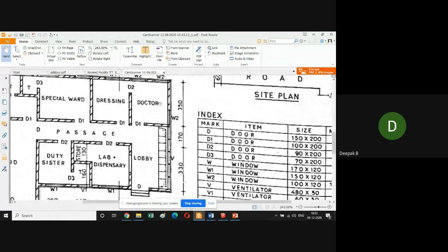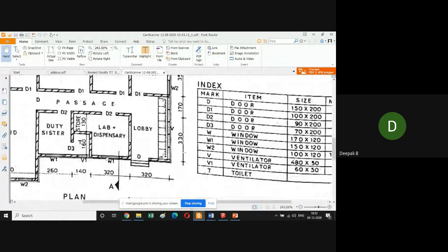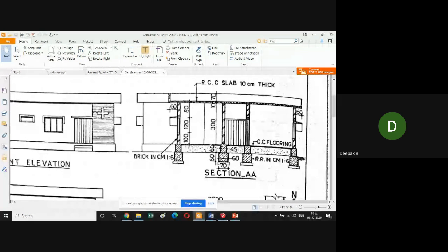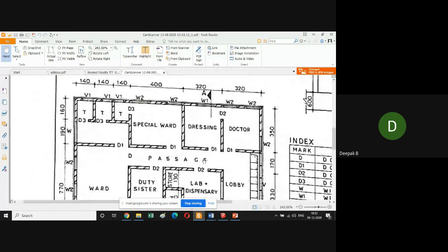And then moving on to the next part, the section line is cutting this wall. It is not cutting the door, instead it is cutting this wall. So here you got to show a fully hatched wall. And then after that, you are seeing this passage. If you are looking from here and viewing this passage,